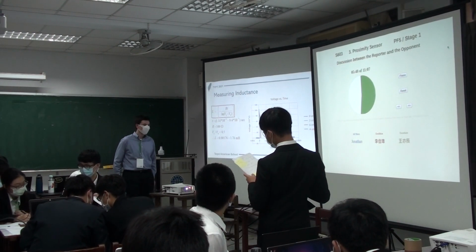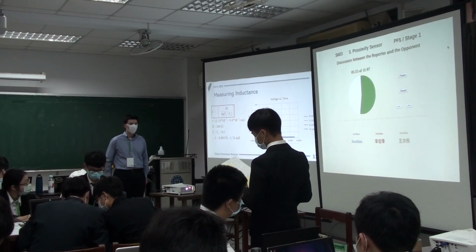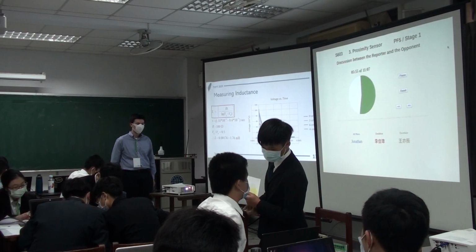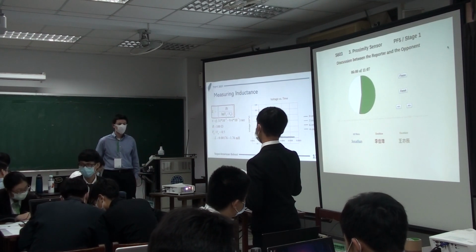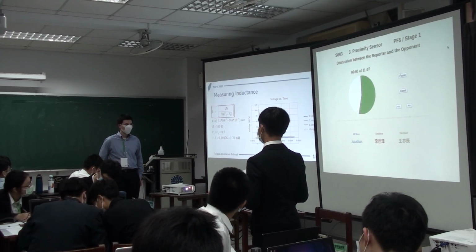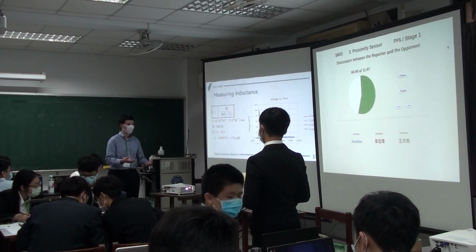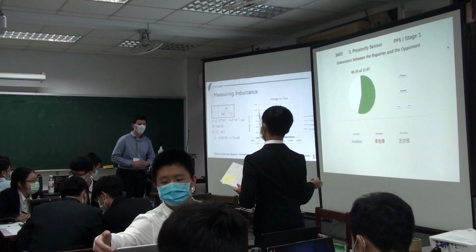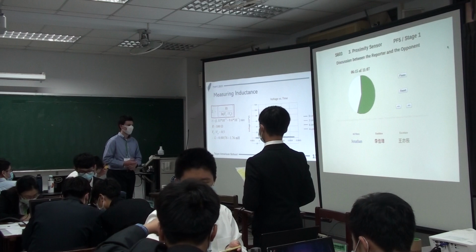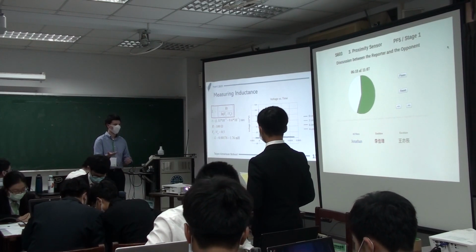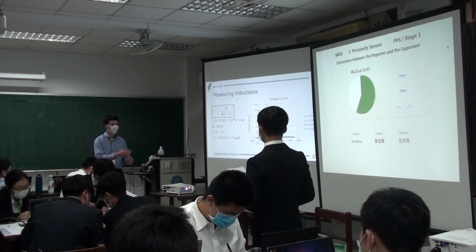Do you think there are any effects that will cause a change in the inductance value in your experiments? Well, as we said, our entire theory is based on the insertion of the rod changing the inductance value. So I'm not sure what you're asking. Another effect? Do you think there's any effect? Well, I think that the two main effects at play for the inductance are the natural inductance of the coil itself, and then the changes due to the presence of the ferromagnetic material.